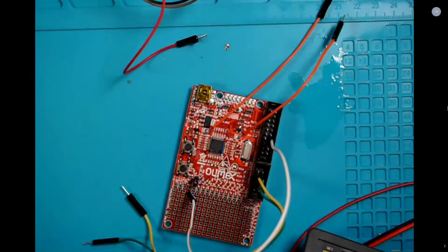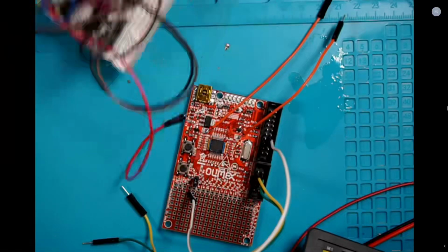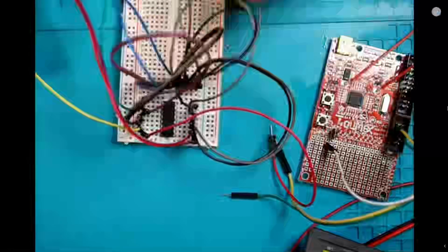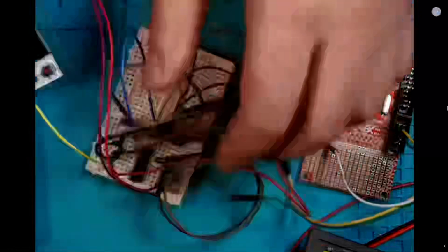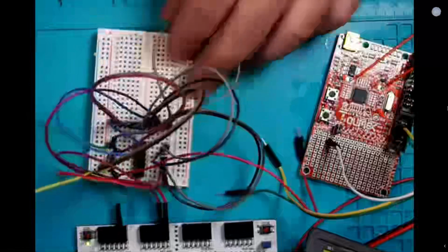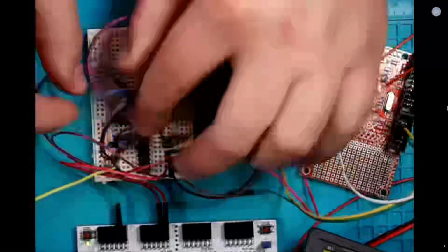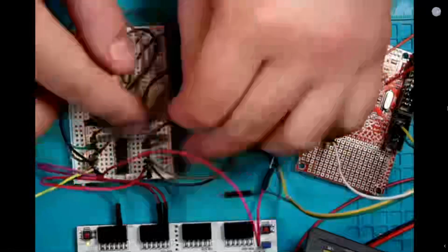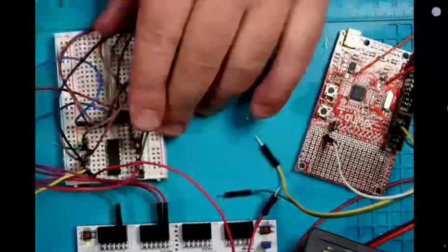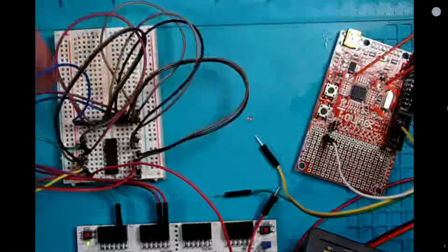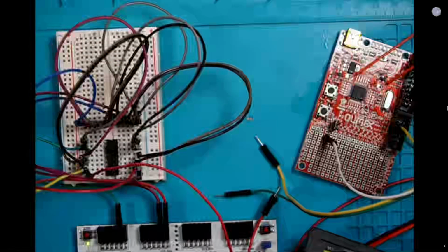All right. So now we need a couple more connections. Let's take a look at this guy right here. All this is, I had this in the slides, a multiplexer board. If you look really closely, let me try to unwind it a little bit just by moving it like this. So here's the multiplexer board. You'll quickly realize that almost everything is actually connected. All these dark and more or less neutral colors, except for the green wire, are connected to ground. So I have a bunch of ground connections here, and those are just ground.